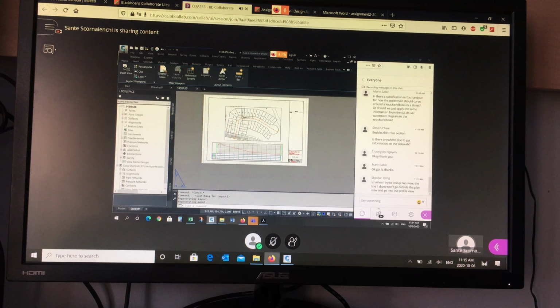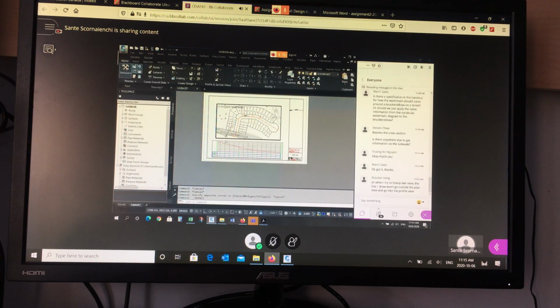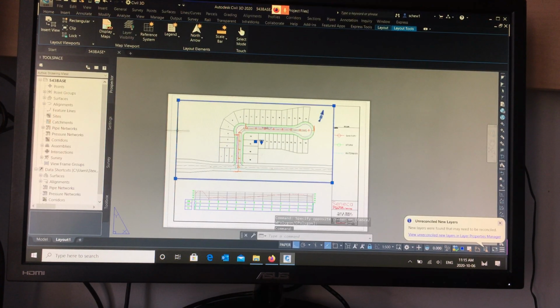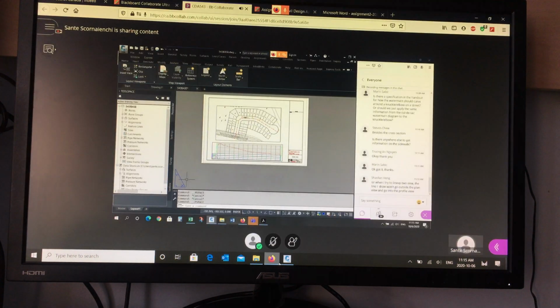Well, if you go into the view, you'll see those stick figures as well. So I'm in paper space, but I'm going into model space through the viewport. Okay. When you're drawing that vertical line, you have to be in paper space. The thing you have to remember is even though I'm in paper space, I can still draw a line and snap to something in model space. So that might be what you're experiencing.